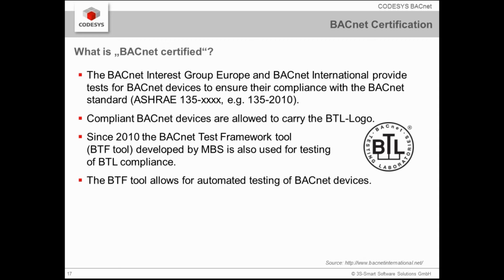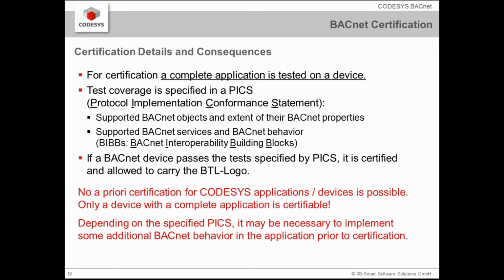The BTF tool also allows automated testing of BACnet devices. What else should you know about certification and which are the consequences? For certification, always a complete application is tested on a device. The test coverage for the certification test is specified in a so-called PICS, a Protocol Implementation Conformance Statement. And this PICS usually contains supported BACnet objects and the extent of their BACnet properties, as well as supported BACnet services and BACnet behavior, also called BIBs, so BACnet interoperability building blocks.